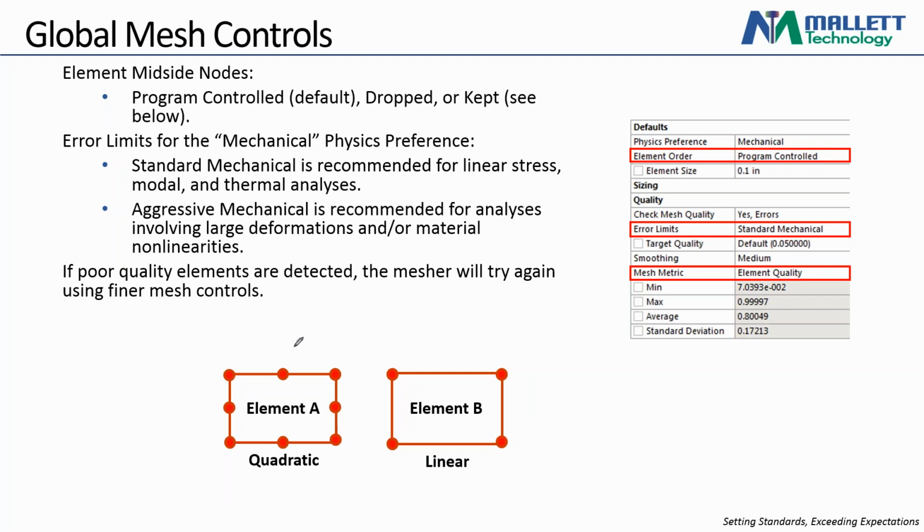So generally, what I would say is tetrahedrons, always quadratic elements. Essentially, linear tetrahedrons are overstiff, and unless you use an incredible amount of them, it's going to be the kind of incorrect answer. For hexahedrons, it's okay to use linear hexahedrons, assuming you have enough through thickness and you're not necessarily interested in stress concentrations if the mesh is too coarse.